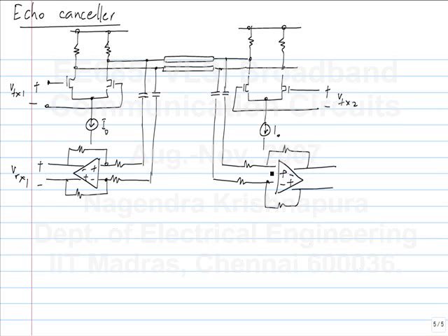Okay, and the values were chosen so that on either side you get a perfect 100 ohm termination. This was 125 ohms and this was 500 ohms, and it's a symmetrical problem, so you can ignore one side and calculate the result from the other side. For echo cancellation, the equivalent circuit is, looking in here, basically 100 ohms to ground in the signal picture.